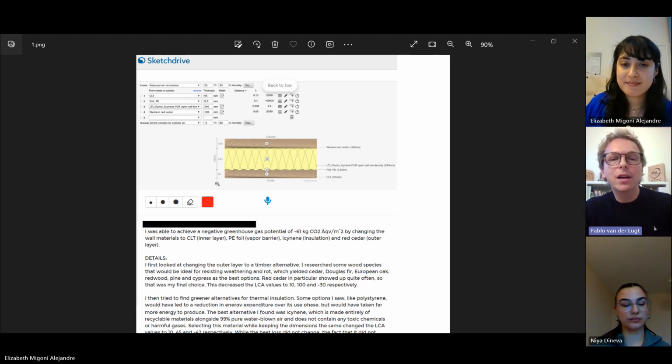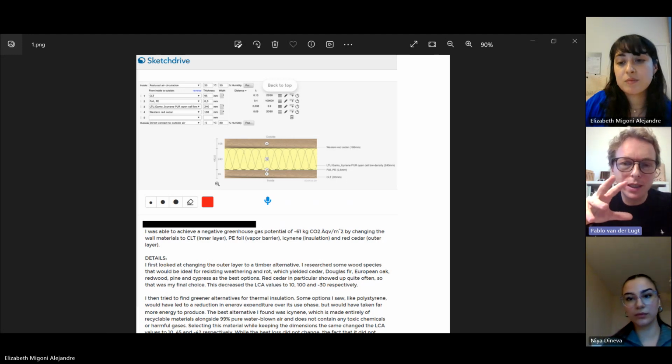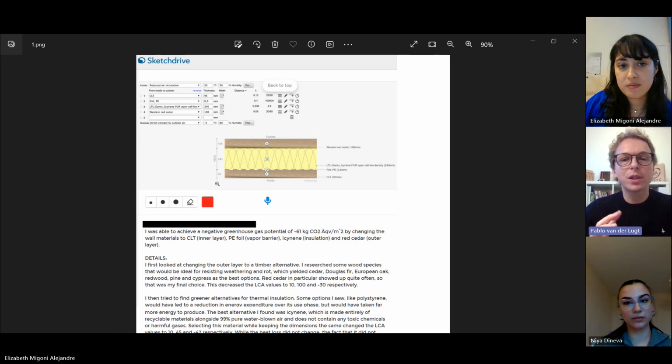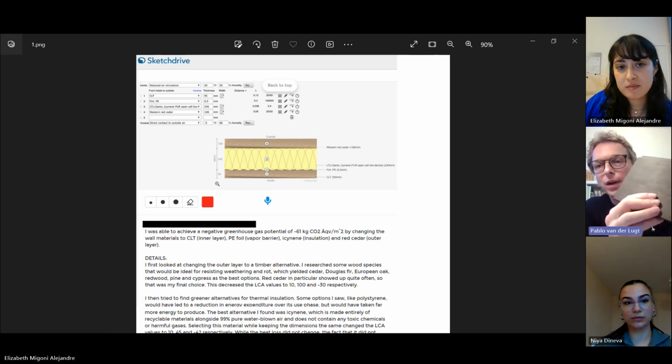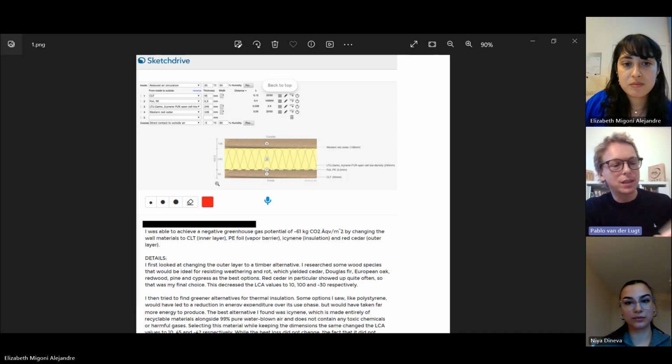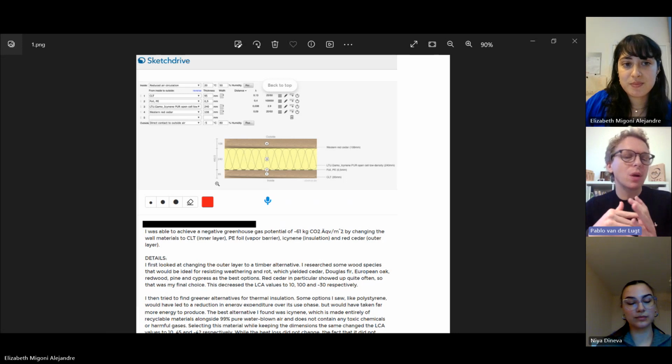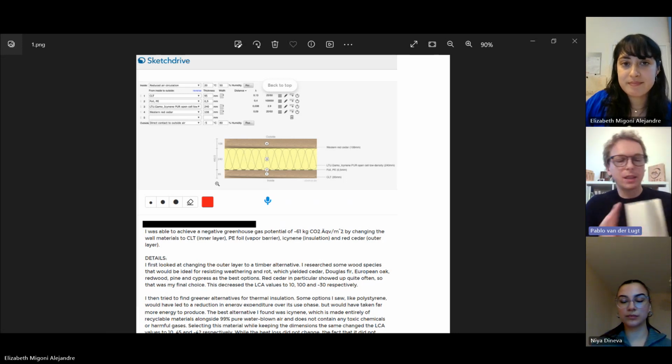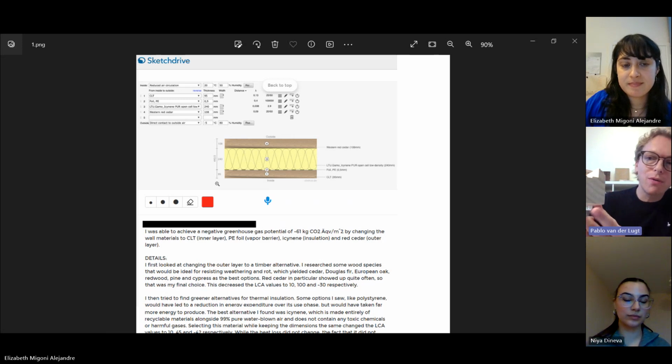And I just wanted to point out, because there were also a couple of questions about that on the forum, that there are a couple of modification technologies, called wood modification, which changes wood or bamboo or any other bio-based material on a molecular level. So instead of impregnating with biocides, this is just a heat treatment. For example, thermal wood, here's an example of thermally modified bamboo. This increases the resistance, makes it very stable, up to durability class 1. That means it's the highest durability class, and it will hardly rot, or will not rot, even in ground and water contact.